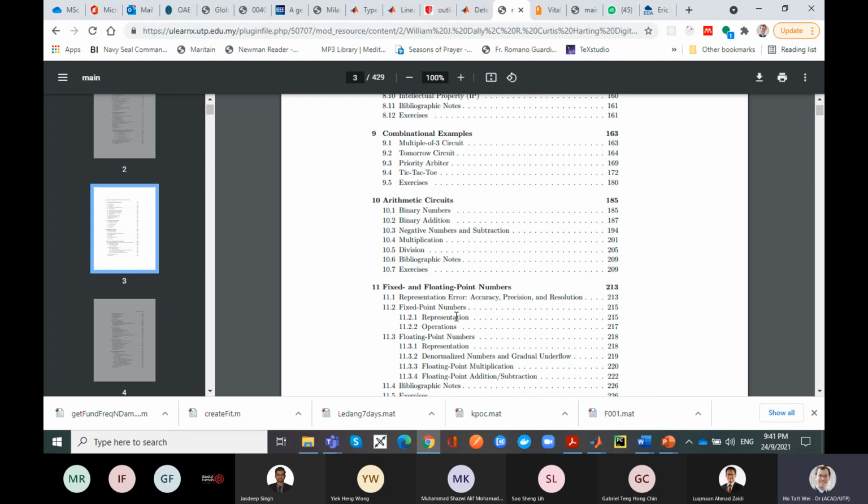But fast forward 20 years now, the bottleneck is no longer computation. In fact, our chips, our digital systems today, they can compute things so fast that it's kind of hard to actually fill them up and keep them busy, right? So you have multi-core. I give you an example. The GPU is the most recent, the best example. You've got, I think, hundreds to thousands of floating point or fixed point cores. What I mean by floating point fixed point cores is basically an arithmetic circuit that can do floating point operation or fixed point operation. Fixed point means you're adding fixed point numbers. Floating point means you're adding floating point numbers. We'll talk about that a little bit more later.